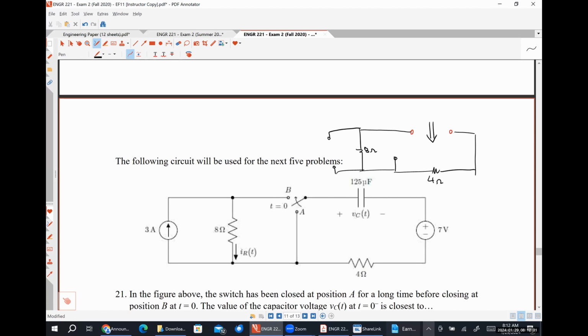We are finding the Thevenin equivalent resistance with respect to a particular circuit element. It is the energy storage element, so that gets taken out. It is an open circuit, and that applies for inductors as well. Yes, we're taking it out of the network and looking in through the terminals left behind. So when we're determining REQ for these transient analysis problems, it doesn't matter if it's the inductor or the capacitor, replace it with an open circuit and look in through those terminals. Okay.